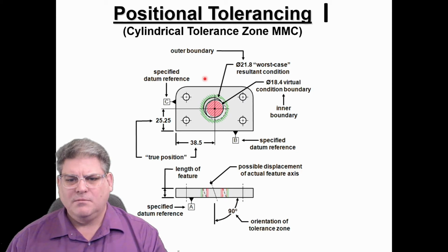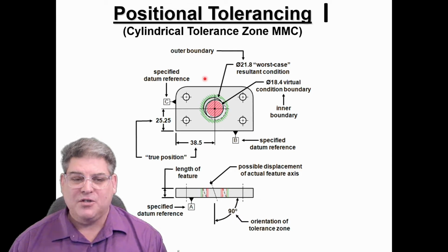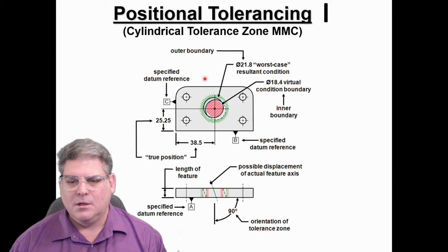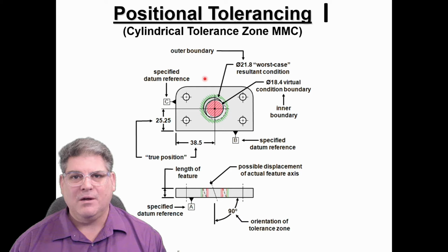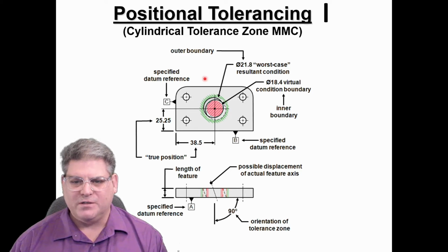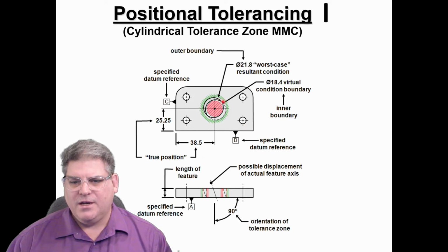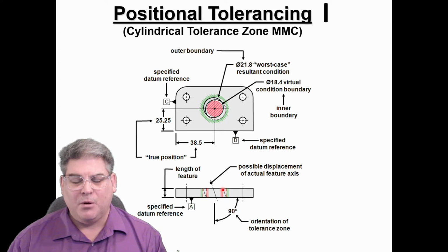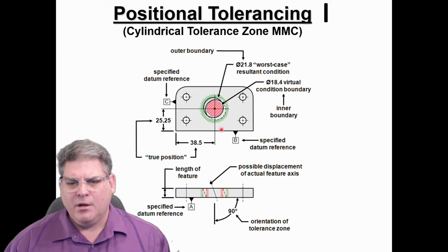So next is we've got a cylindrical tolerance. So what is a cylindrical tolerance? And this is something you may actually see with parts that need to get mounted together, probably not transistors, but you may see it with switch mounting, okay, where they start to refer to how square the hole is to the surface. And so here's a great example where they give this tolerance, and what they're looking for is how far off perpendicularity the hole has been drilled, okay, or in this case stamped.